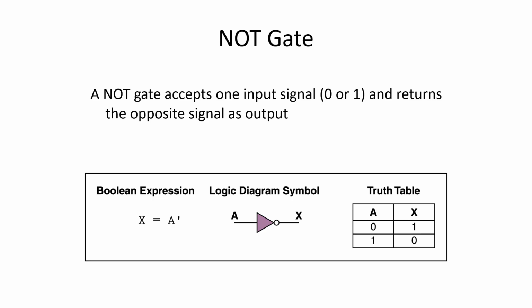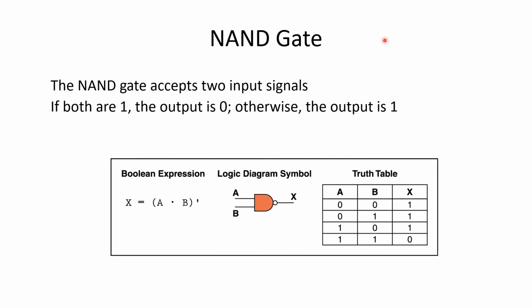In systems where an action must occur when a condition is not true, the NAND gate is used. The NAND gate is a combination of an AND gate followed by a NOT gate. It performs the inverse operation of the AND operation. A NAND gate outputs 0 only when all inputs are 1, otherwise it outputs 1. In simple terms, it outputs the opposite result of the AND gate.